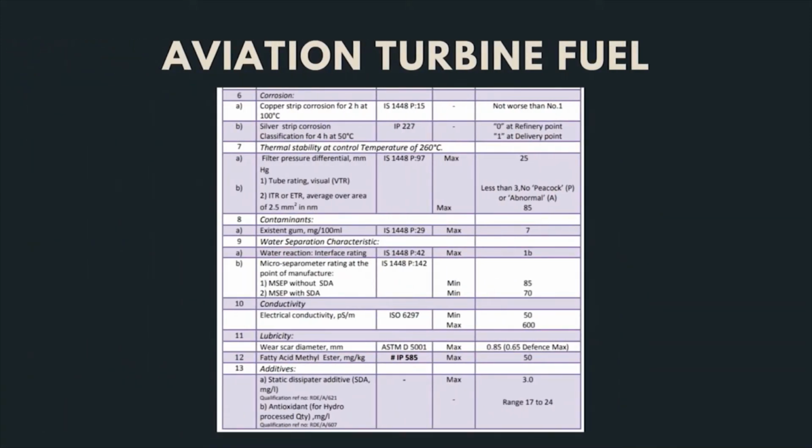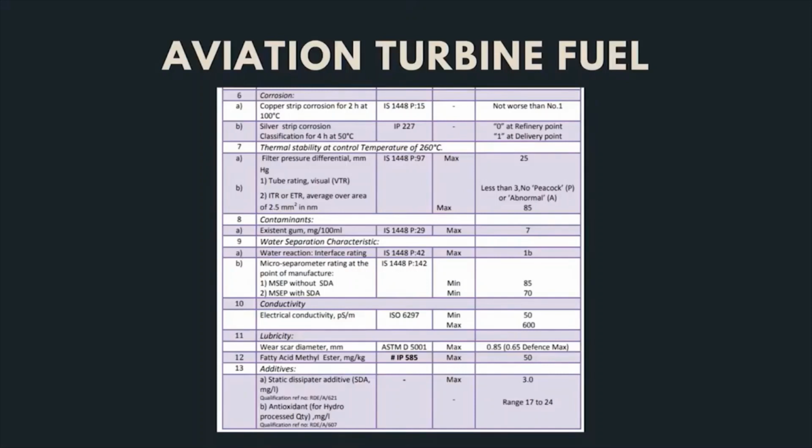Thermal stability at controlled temperature is an important test. Then water separation characteristics. Water should not be present in aviation turbine fuel, because if water is present, at a high altitude it may get converted into ice, and that may plug the fuel lines and create a catastrophic incident. So water presence should be nil, and then conductivity is also an important test for aviation turbine fuel.